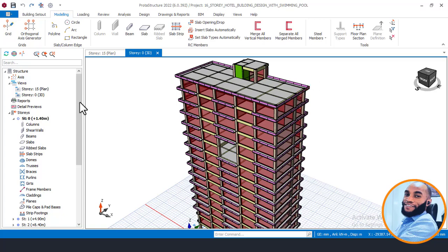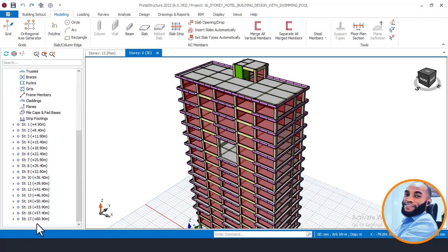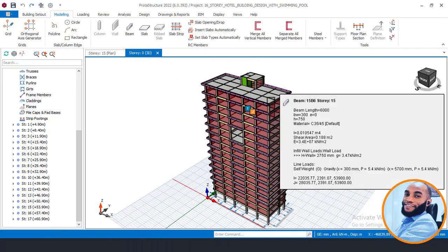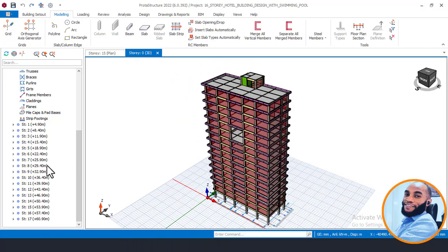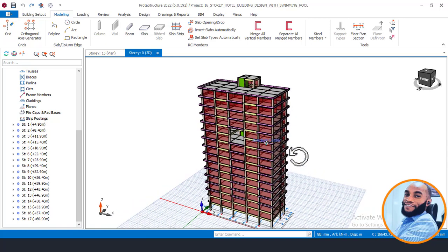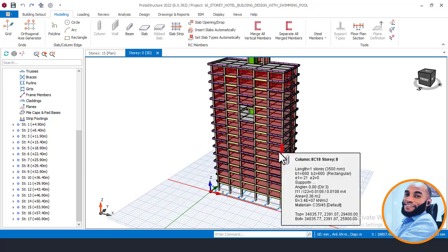Okay. And looking at this right now, our total height of story is given to be what? 60.9 meters at this 17th floor. 60.9. So this is a high-rise building already. So knowing that a medium-rise building starts from 10 meters, which is basically between 3 story and 2 story, we have our 10 meters between there. So that means we are going to start to apply our live load reduction from 10 meters.